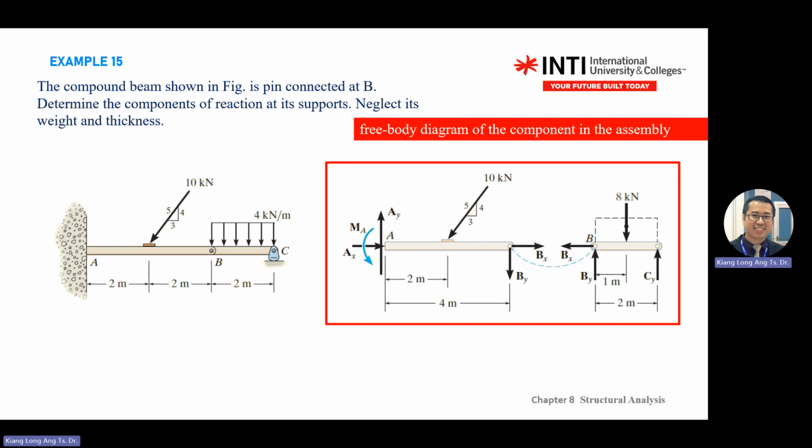Yeah, so have this kind of practice for the BX direction. When you cut the things or you remove the pin, try to imagine that actually the two members tend to join together, so the arrows point at each other rather than push away. Okay, so this is the common sense or correct method of doing analysis in structural analysis. Then for BX, BY, the BY depends, as long as they are in opposite directions.